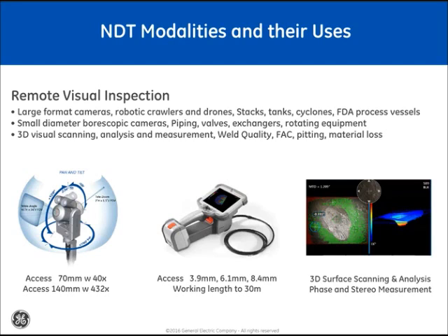is a look at when you're doing remote visual inspection, you're going to ask these questions. What do you want to see? What is the size of the area that you need to inspect? Or what are your anticipated environments in the inspection area? Are there residual products? Or what is the temperature? What kind of access do you have? And what is the travel path to get to the target?